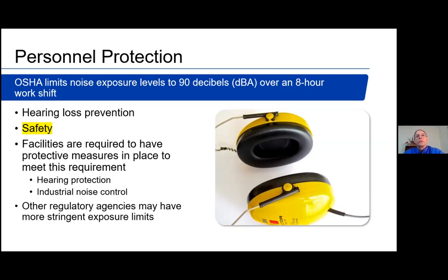Within the European Union, we see a limit of around 87 decibels for that same 8-hour working period. And then in some other European areas, we see limits varying from 75 dBA up to 100 dBA. So you have to be very aware of what the requirements are in your specific area to make sure that you are following any of the necessary regulations that would govern your facility.